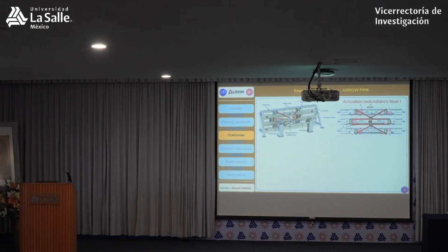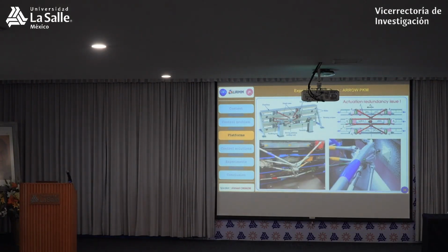So this is the robot, this is the kinematics, we see the 6 motors, and the application is here for machining. I will show you a video of machining of this piece with a pyramid shape. This is the moving platform, where the tool is fixed, this is the parallel platform, and the linear actuators are here. This one, this one, this one, and you have 3 here also.